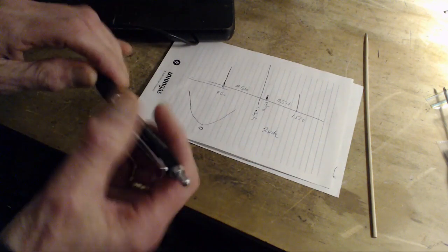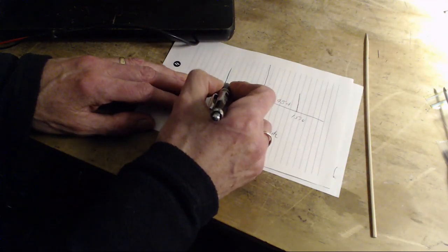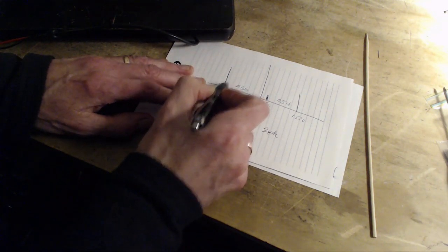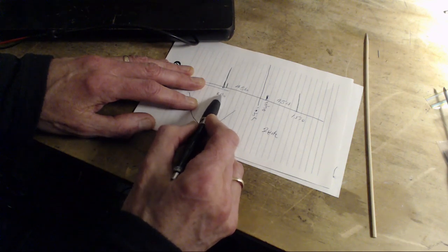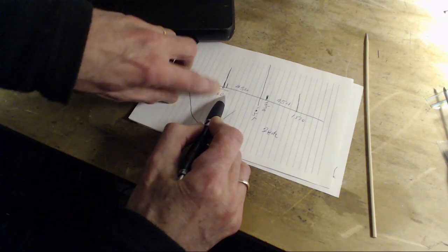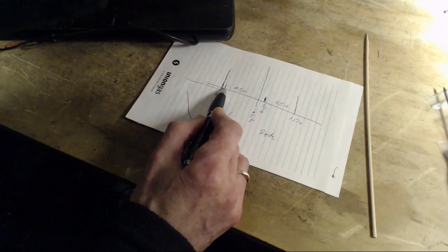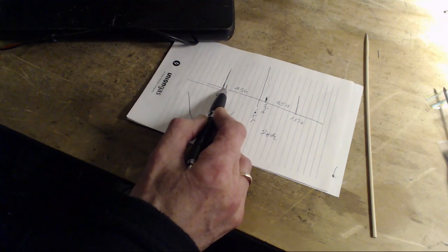If you have another interfering signal, not up here, not an image, just another signal right here, maybe a noise signal, also, let's say 2 kilohertz apart. So you have your signal you're after at 600, so there's a carrier here from some broadcast signal, and then at 602 there's a noise signal. There can't be another broadcast signal until you get to 610. But at 602 there could be a noise signal.